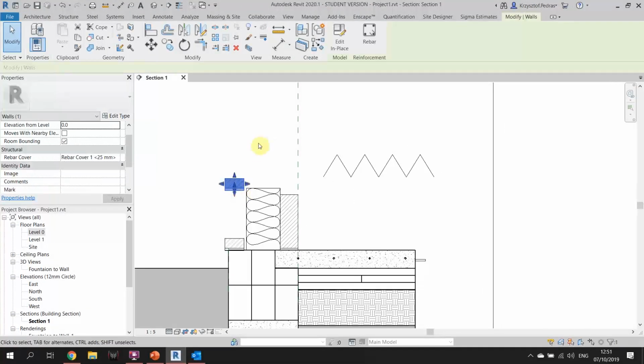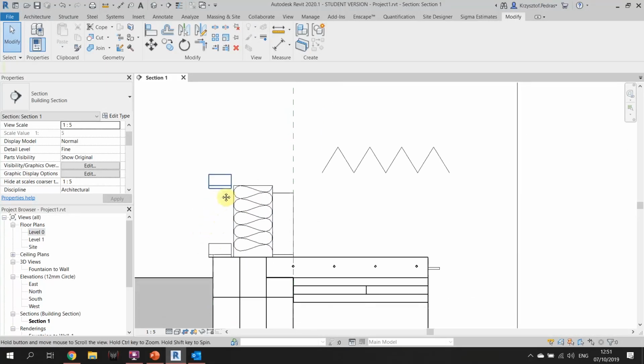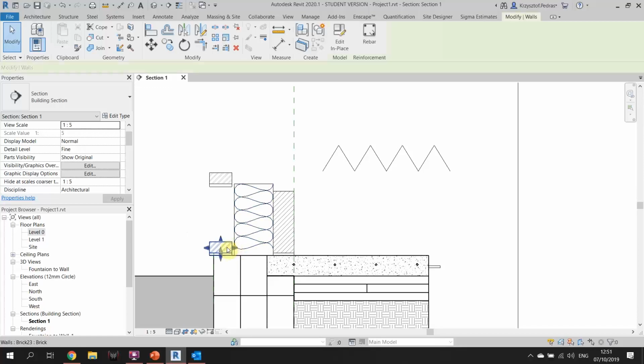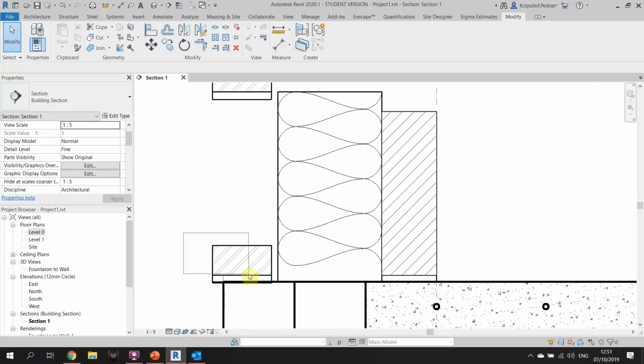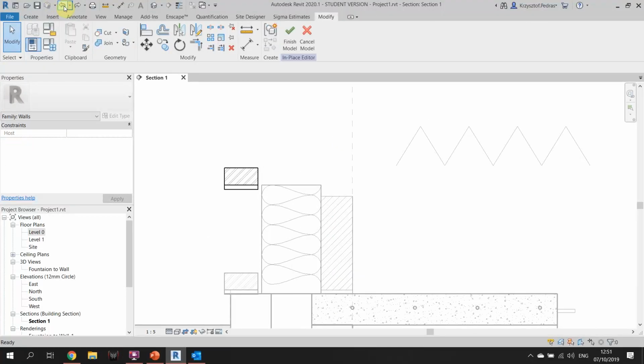You see that the brick received the pattern, and that is the case, a stupid case that's happened before, that those bricks are bound to the reference plane, so they will keep going back to that reference plane. So I'm just gonna undo that to avoid it.